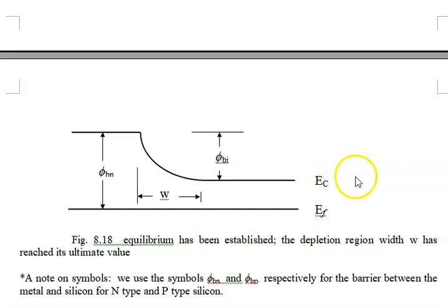And here's the general rule, and we'll prove it later. Whenever one goes in an N-type silicon, which is hooked up, if you will, to a metal whose work function is higher than the silicon, then the bands will always bend up. And that's a big deal. And I've tried racking my brain to figure out a nice mnemonic to remember that.